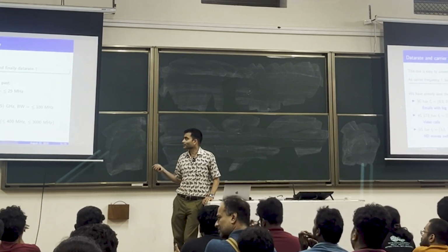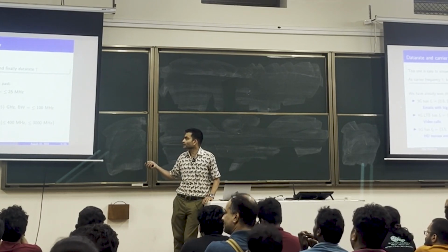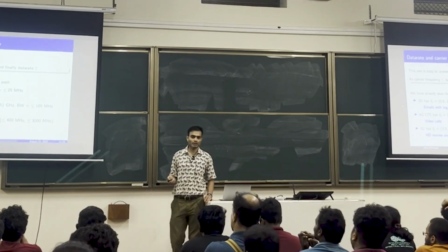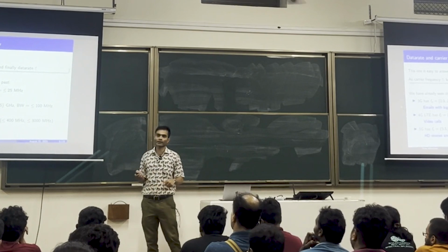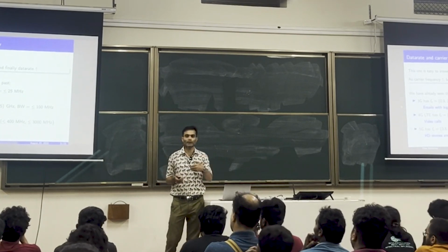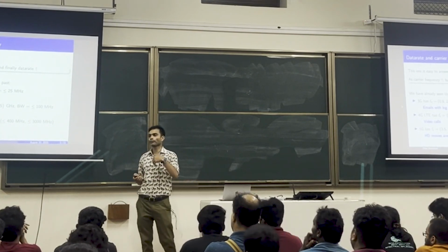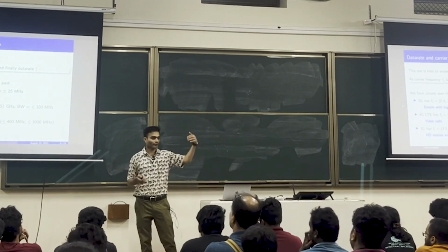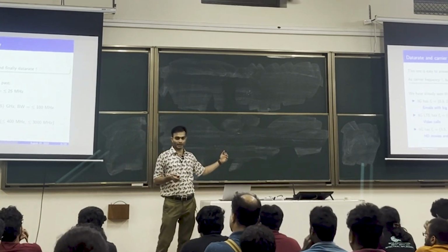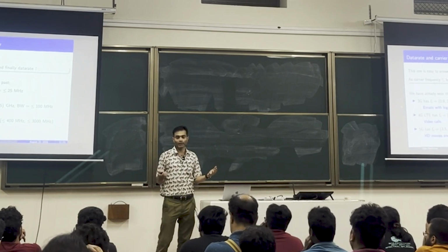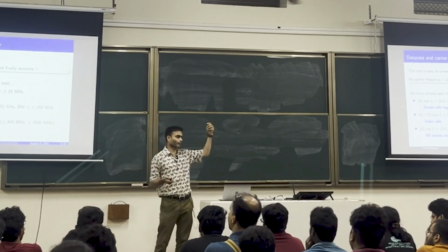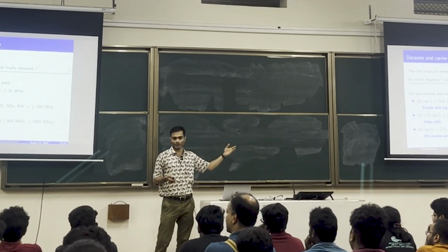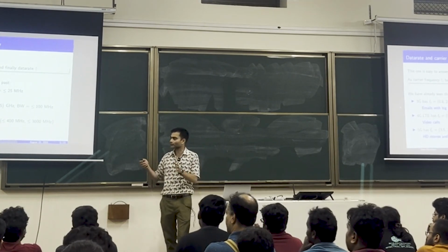There's nothing physically significant. You can see, for example, all of these frequencies except 26 gigahertz are roughly in the same range. And there is physics involved over here, because if you start increasing the frequency too much, the absorption by rain and fog starts to increase. So you don't obviously want to work over there. In the atmosphere, there are certain frequencies which get absorbed by molecular transitions. You want to avoid those, right? So there's some basic physics which tells you the range.